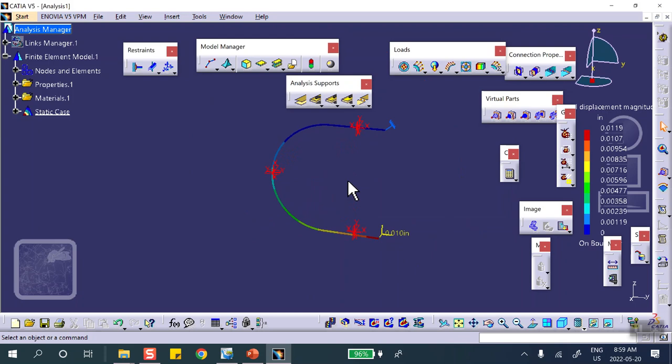There we are. Now you might ask yourself, and we did talk about this a little bit yesterday, why do I bother doing this? It took more work trying to put these points and lines and things like that. Can I not put it in the sketch? The answer is yes. But if your curve is not fitting in a sketch, meaning fitting in a plane, you can't put it in a sketch.